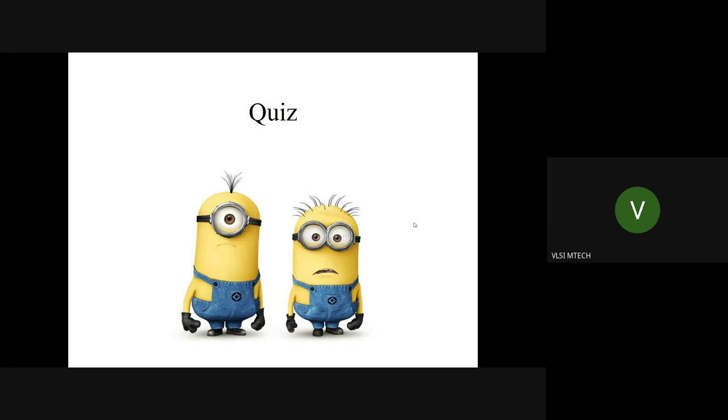If you see carefully, Intel's node names have gone from Intel 7, Intel 4, and then this 18, which is some angstrom. They have removed the nanometer from the end. It's no longer 65 nanometer node, 22 nanometer node. It's just Intel 7. It's not 7 nanometer. So the gate lengths are stuck at the order of 10 nanometers, 12 nanometers. We are not thinking of scaling them further down because we don't have that gate control yet.